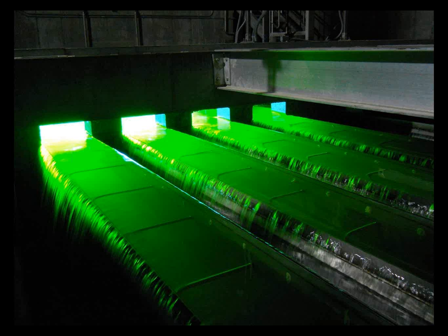This is the treated water going over the weirs. You obviously see the UV light is on. The water comes in, fills these troughs, and then runs over. Again, when the flow stops coming to the bulbs, these stop running over, and water is contained in the weirs. Plenty of water in order to keep the bulbs wet, and also because we want to keep some of our bulbs on at all times.